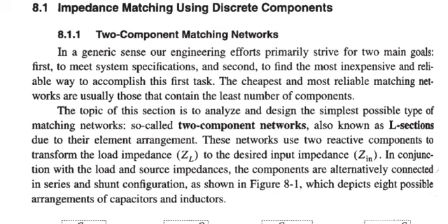As I stated earlier, the transmitter impedance ZT is, let us assume, 150 plus j75 ohm. The impedance that the matching network should present to the transmitter is the conjugate of the antenna's impedance. If the antenna's impedance is 75 plus j15, the impedance available at the transmitter side should be 75 minus j15, which is the conjugated version of the load impedance. So that is going to be my target, right?